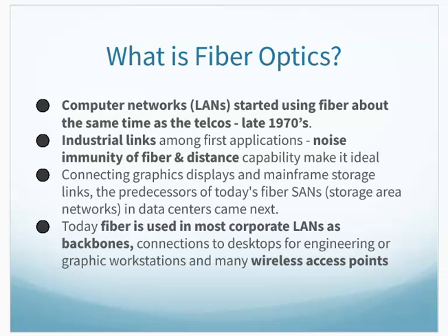In our computer lands, our computer networks started using fiber optic in the late 70s for backbone connections, which we'll look at here in a minute. Industrial networks started using fiber optic for noise immunity as well as distance. If you think about large manufacturing plants, they're spread out over distance. You also think about all the machinery moving in there, robotic arms, conveyor belts, motors, those sorts of things, moving things around. All that is electrical noise that would affect your copper cabling. If we put fiber optic cabling in, it's unaffected, as well as you have distance to get things out to various parts of your plant.